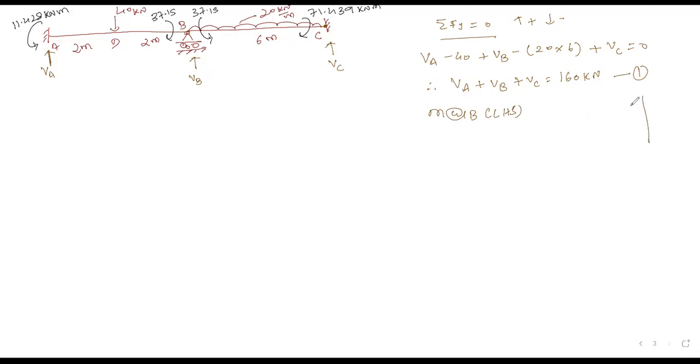Suppose we cut a section, left and right. On left side, clockwise moment is positive and anti-clockwise moment is negative. On right hand side, anti-clockwise moment is positive and clockwise moment is negative. Okay, it will be applicable for each and every problem.